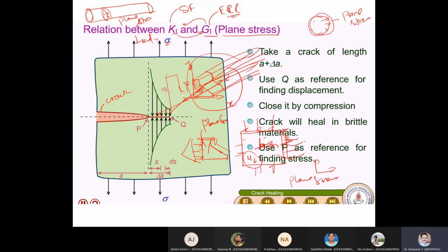I hope you understood. If you take composites for a typical aircraft wing, the skin is about 3 mm composite. But if you see the structure in that 3 mm, there will be something like 20-30 layers of composite film, each 0.15 mm.